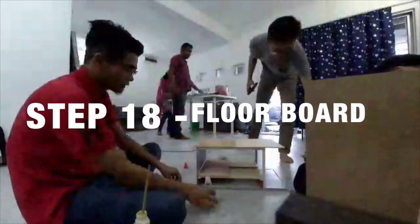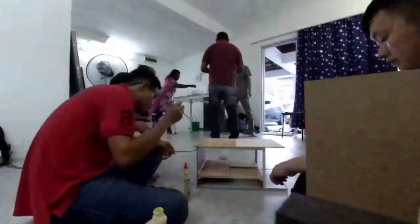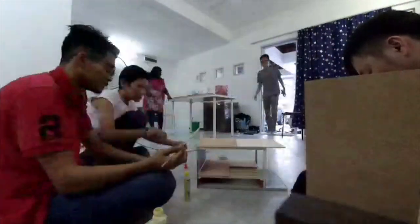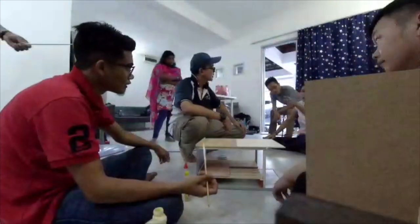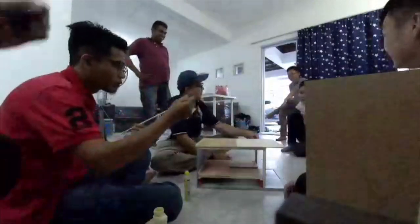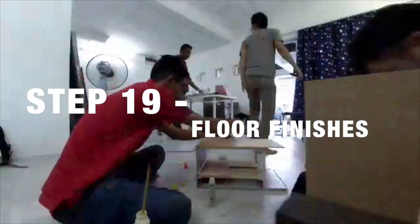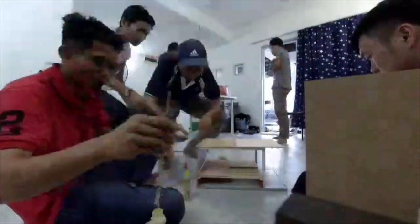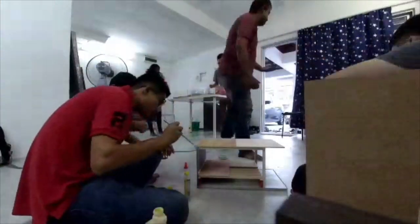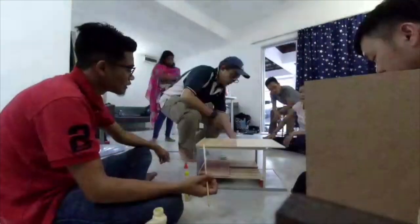Floorboard, again similar to suspended timber ground floor. For upper floor constructions, we are using plywood, and this time around we didn't cut the wood into L shape. Floor finishes are also similar to the ground floor constructions, and on our working model we are using book wrapper and glue it on top of the floorboard.